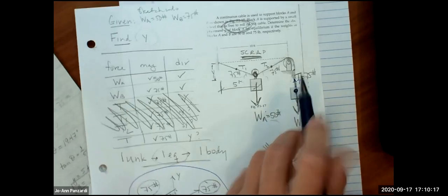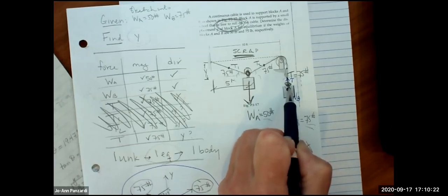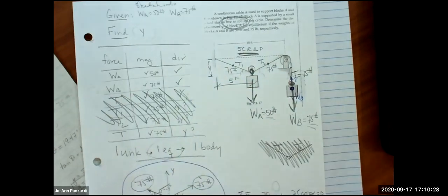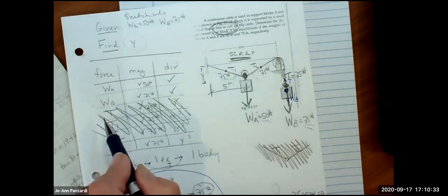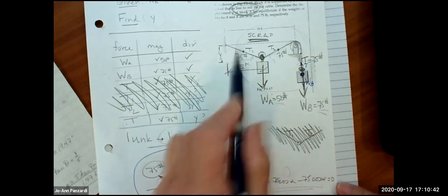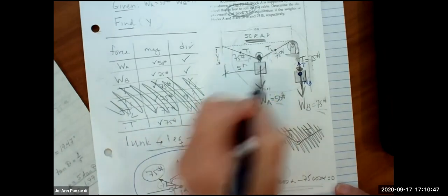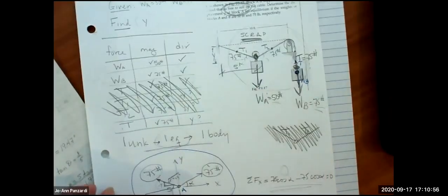Well, right now we're doing statics of particles problems, right? If we pick this point right here to do our free body diagram of, the only equation we have is sum of the forces in the Y. Right? And we're always choosing a point where all the forces are, including the unknown. So we're not doing a free body diagram of the whole thing, because then we would have to do sum of the moments, and we're not doing sum of the moments yet. So you want to pick the point where all the forces converge. Like you wouldn't want to do it over here because it wouldn't help you.